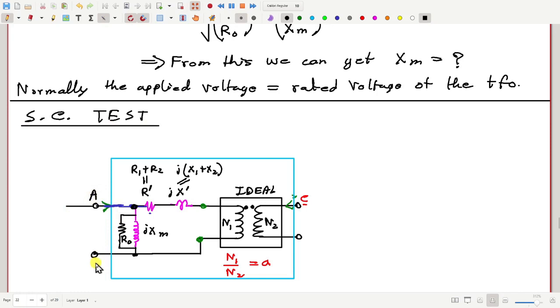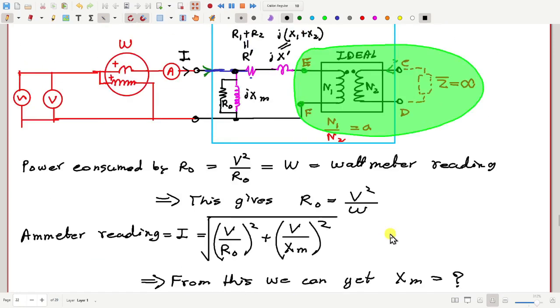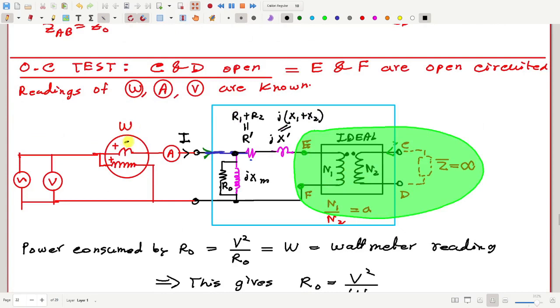Okay, so short the terminals A and B. And between C and D, let me connect an ammeter, wattmeter, okay, this is the current coil, this is the pressure coil. In the previous diagram also, I forgot. Anyway, from the symbol you can recognize that this is the current coil because this has fewer turns, so less impedance.